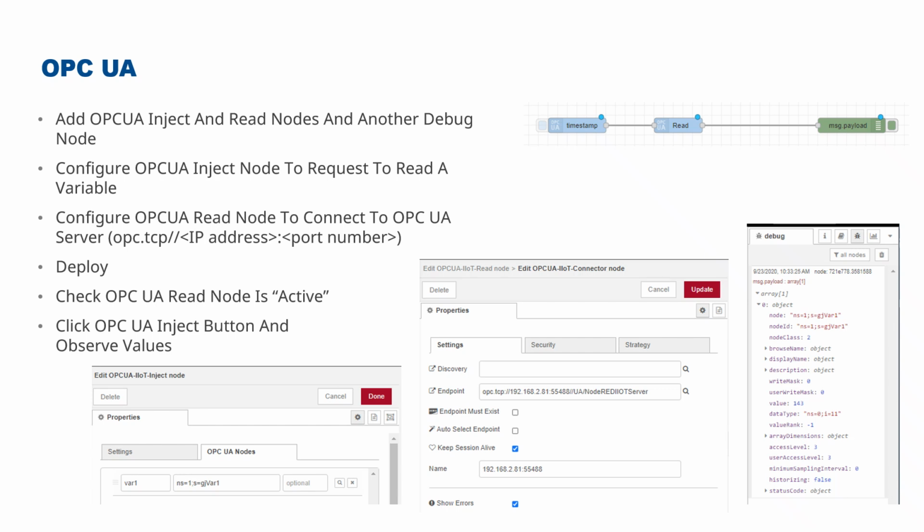But OPCUA is normally preferred for PLC type applications. And the other thing about OPCUA is, with that timestamp, it means that you've got a lot of built-in support for things that with MQTT, you'd have to add that separately. So OPCUA is ideal for PLC type data and ideal for data that's transferred on a time basis. MQTT is also very good, but more for generalized data, but it would really depend on what your remote device uses. So I would recommend OPCUA would be your preferred protocol to use, but MQTT might be used for a database in the cloud, perhaps like a data lake, if it didn't support OPCUA.